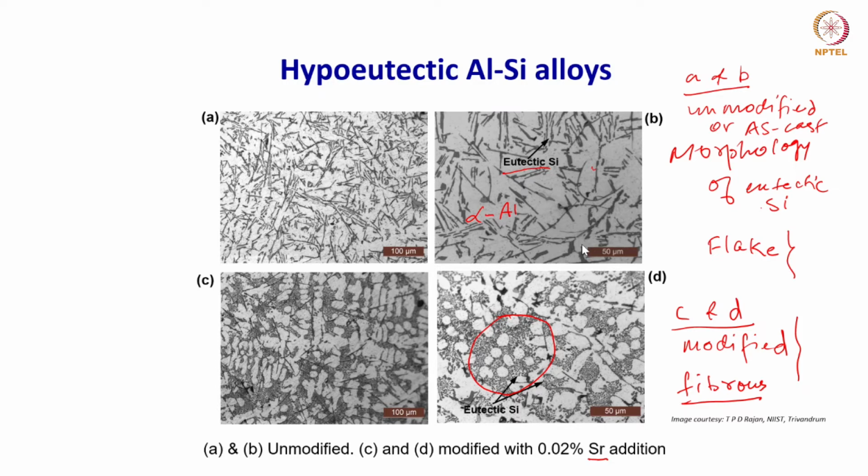It does, and it is continuously rotating, all the time, whenever the car moves. So there also you need a material which is resistant against wear and tear, and therefore a material which should have high hardness. The silicon phase is the one which will provide that property, and that is why these kinds of alloys are so commonly used in those applications, particularly in automotive.